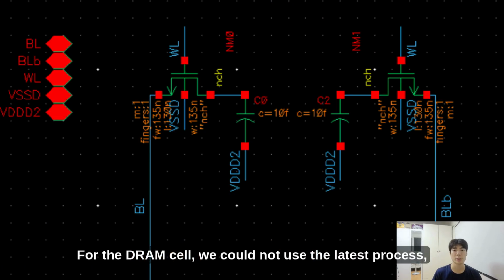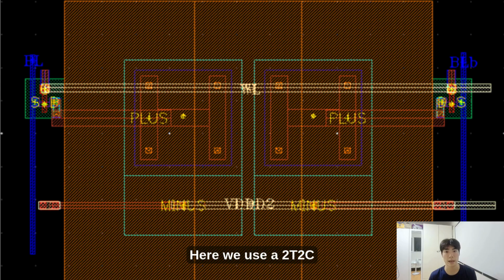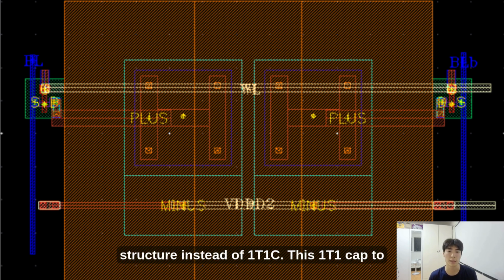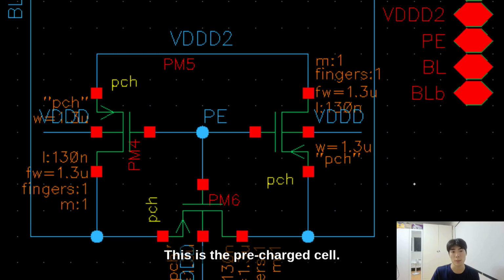This is the DRAM cell. For the DRAM cell, we could not use the latest process, so we used MIM caps. Therefore, the cell size is large in layout. Here we use a 2T2C structure instead of 1T1C to achieve a more efficient read operation using the sense amplifier. This is the pre-charged cell.